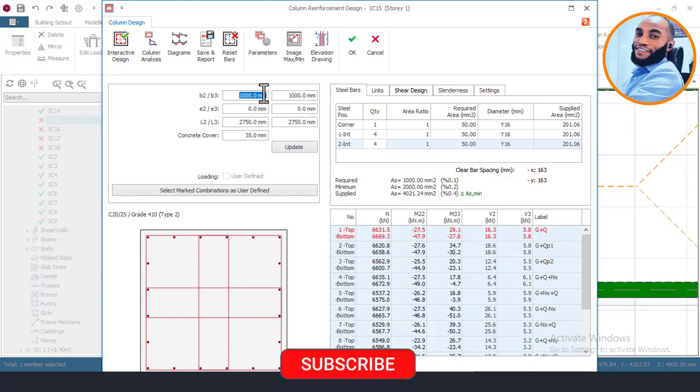25 diameter bar is not really that much for a high-rise building. Any client that can afford to build a high-rise building should be able to afford 25 diameter bar. And also, since it's a high-rise building, you need a bigger diameter bar like 25 and 20 to be able to carry the load efficiently. Although, I'll just give you my own advice on that.